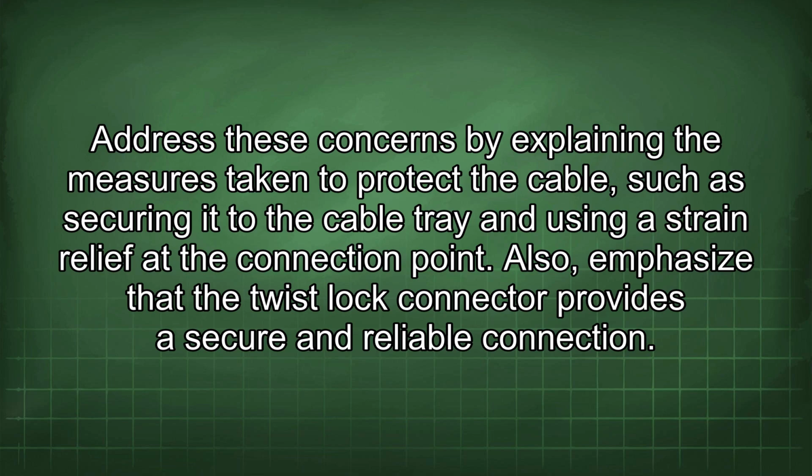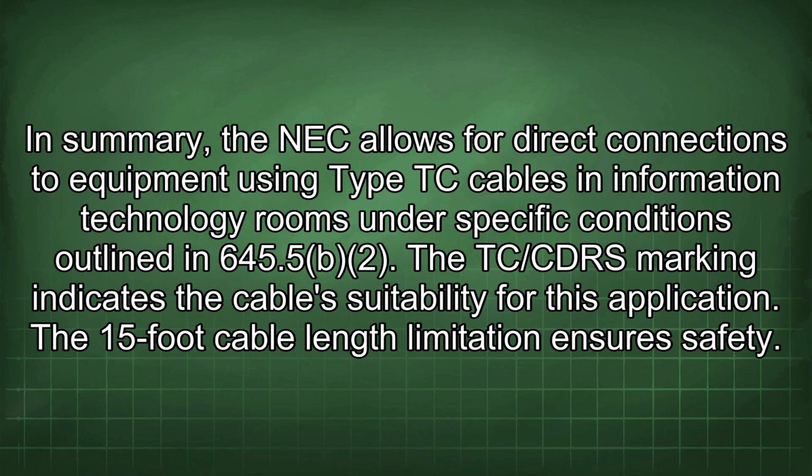Also, emphasize that the twist lock connector provides a secure and reliable connection. In summary, the NEC allows for direct connections to equipment using Type TC cables in information technology rooms under specific conditions outlined in 645.5(D). The TC/CDRS marking indicates the cable's suitability for this application.